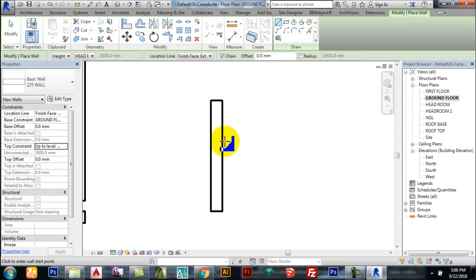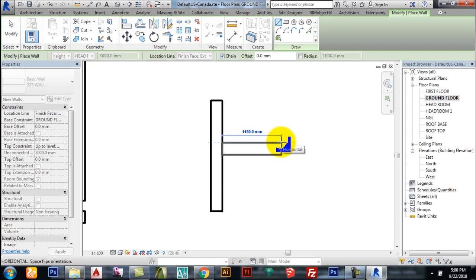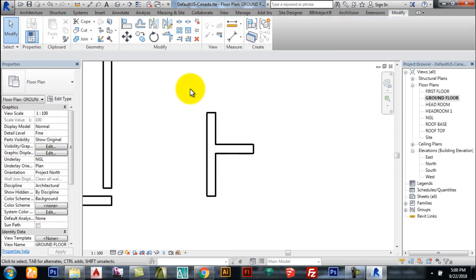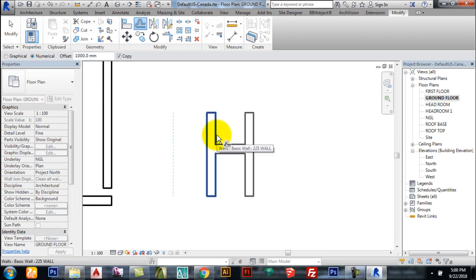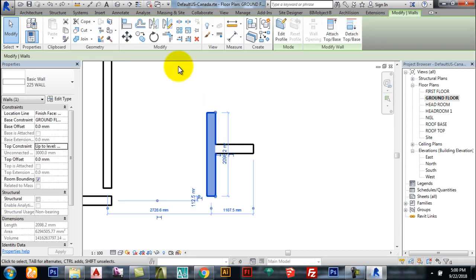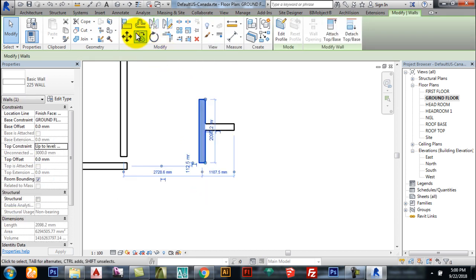Create similar. So imagine I create a line of 1000 here. Then I click enter. So this is 1000 here. So I now click on offset and input that same 1000. Then I try to offset it. Let me do it now so you see what I'm trying to say here.